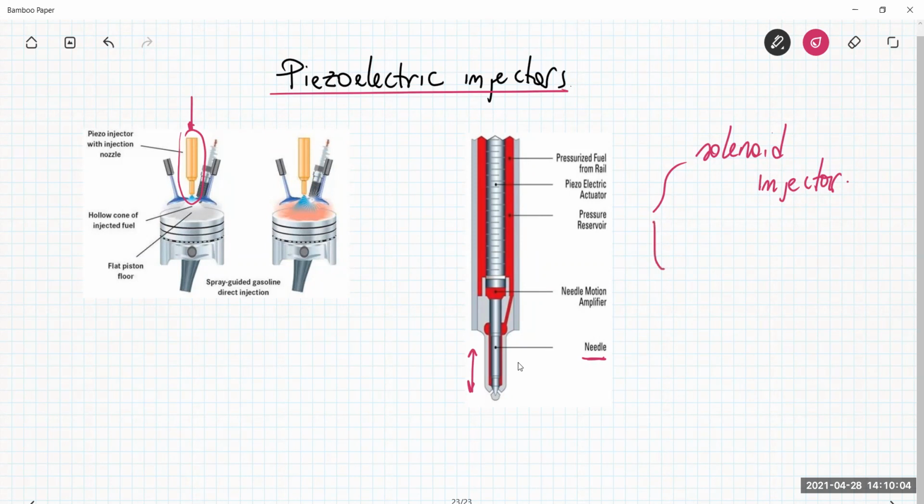And then you can have piezoelectric injectors. The advantage of having piezoelectric injectors is that you can have very precise, very fast sub-nanometer movement. This helps in having very fine-tuning and precise control of the quantity of fuel that you are injecting into the combustion chamber, helping to optimize the behavior and the performance of the thermal engine of the vehicle.